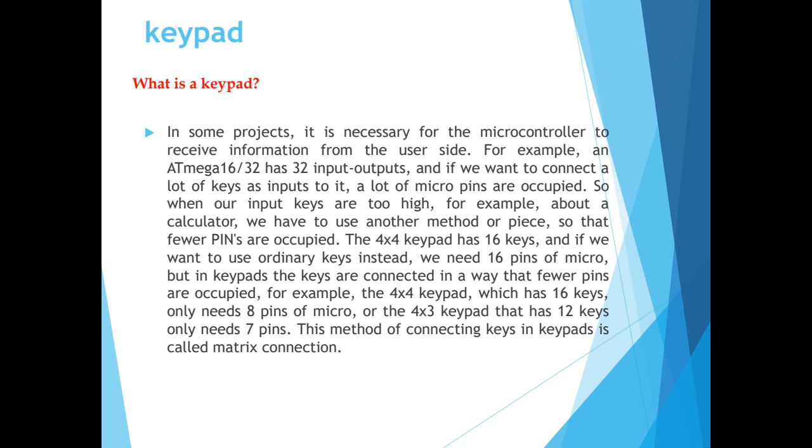Then for interfacing these 16 keys with the microcontroller, we need 16 pins of the microcontroller. Then they would be busy, and what does it mean? It means that the microcontroller can't be used for other tasks. We can't interface other devices to it because most of the pins of the microcontroller are busy.